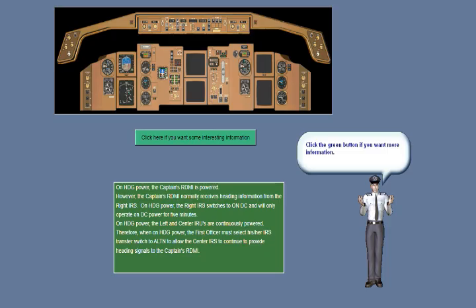Electrical power from the APU flows through the APU generator breaker to the tie bus. The APU generator control switch normally remains in the on position. Regardless of APU operation, the APU generator off light will not normally illuminate when the switch is on. The APU generator off light indicates that the APU generator control switch is selected to off, or that a generator fault has isolated the APU generator.